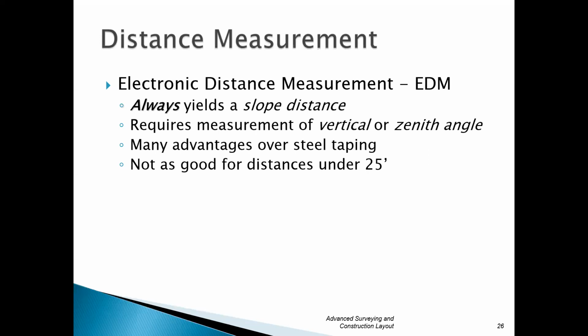Do keep in mind though, I'd say for distances under 50 feet, even sometimes an EDM is not going to be as quick, nor is it going to be as good. There are errors associated with that distance in an EDM, even though they're small. It's probably better not to do it. And like I said, 25 feet, you can steel tape it 5 times quicker.